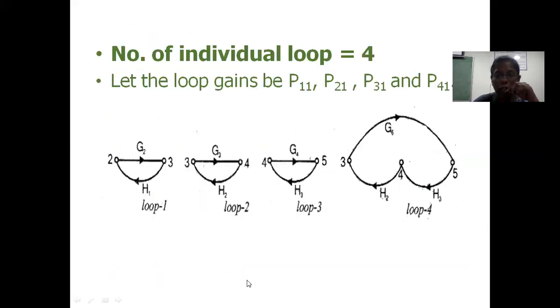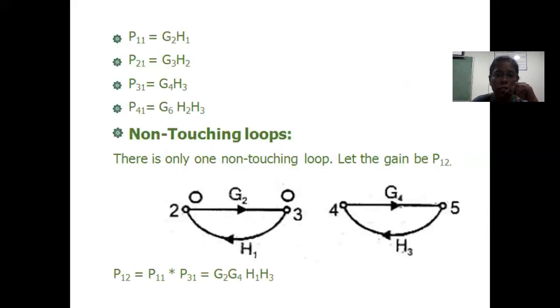And if you go on again, you have to compare whether you have any other combination of two non-touching. But here, we see that there's no other combination of two non-touching available, and three non-touching also is not available, four non-touching not available. So likewise, you have to check it for all the combinations.